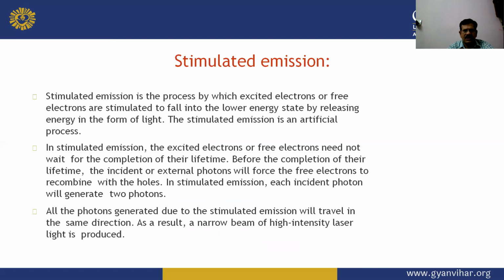Next, what is the stimulated emission in the laser diode? Stimulated emission is the process by which excited electrons or free electrons are stimulated to fall into the lower energy state by releasing energy in the form of light. The stimulated emission is an artificial process.